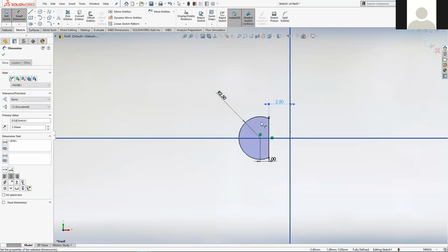So in this one, we're approaching it in the opposite way. We're creating a profile shape first. We're defining its position as well. So the shape of this has been defined by the radius there and by that figure there. But its position in space is defined by that. So that's relative to the origin or the primary planes, and the fact that it's coincident with that plane there. So the two things define distinct elements about it. One is the shape, one is its position. This position one, we may come back in and modify that later on.